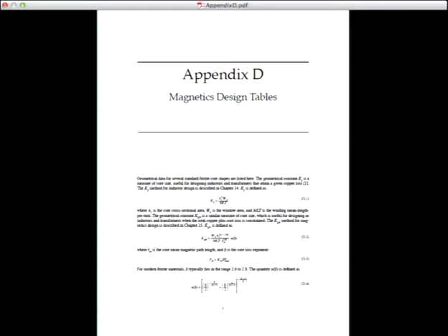So to get KFE, you actually have to go to the plot of core loss versus flux density. And I think the problem asks you to look at a figure in Chapter 13 that is claimed to be a typical material, but the problem is saying, let's suppose our core is made out of that material. Figure 13.20? Okay, thank you.